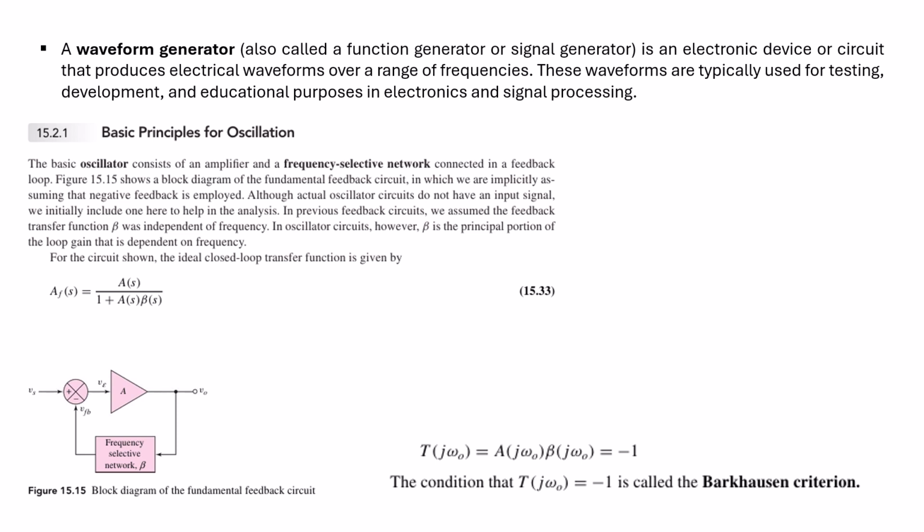So in that case it will continue to oscillate, and taking advantage of these oscillations we can have different waveforms or different signals. This is also called the Barkhausen criterion. The criterion is that the transfer function T, that is the product of gain and feedback, AB, should be equal to -1. Actually it should be a little bit higher, otherwise it may drop to 0 and may not keep on oscillating. But this is the ideal case. Ideally it should be -1.